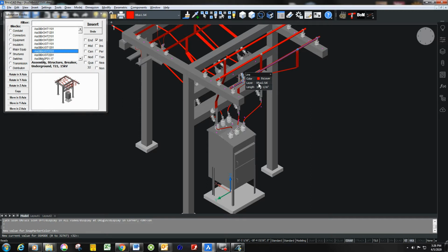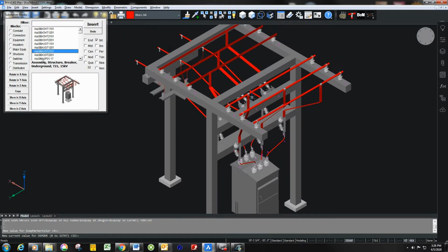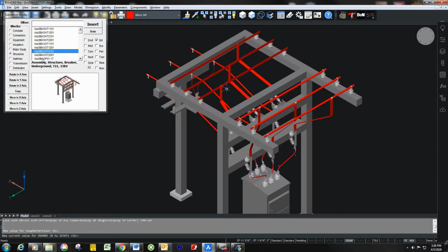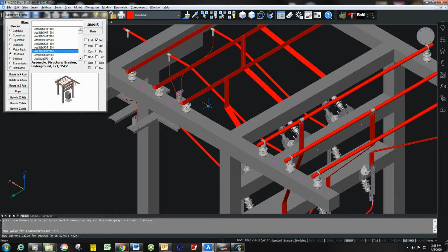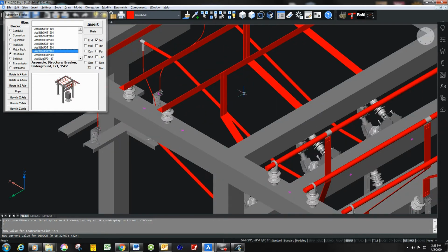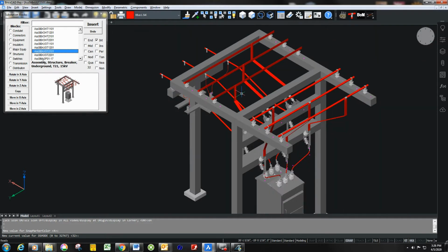It's a 2.5 inch pipe bus. Excuse me, on the main bus is a 2.5 inch pipe bus. We're using some flat bar here for jumpers. They could be easier to be conductor. We're using an angle bus for the transfer bus. The advantage of transfer bus is you don't have all the expensive connectors. It's just 4 bolts and some holes. Somebody's got to make those holes, however.